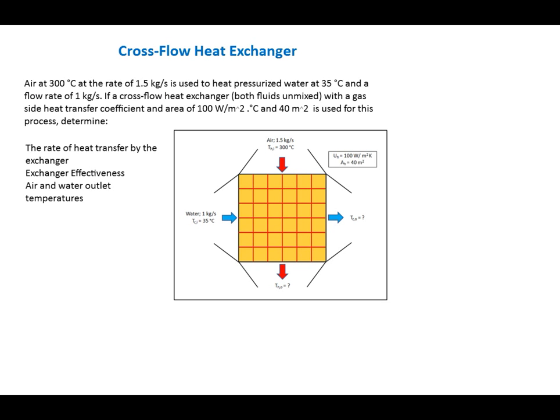Now let's see how ThermoFlo can be used to solve classic heat exchanger analysis and design problems using the methods developed by Kays and London. The solution procedures for these problems usually involve chart lookups for effectiveness and NTU for various types of heat exchangers. All these are programmed in ThermoFlo. As we mentioned earlier, the user can optionally define their own heat exchanger behavior based on their experimental data as well.